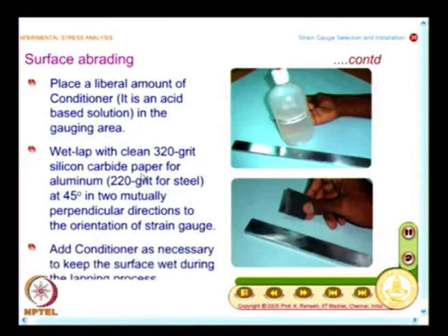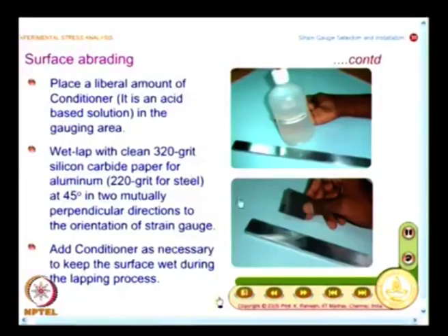And here you are not testing your muscle power to rub the surface with full force, that is not what is anticipated. What is anticipated is to prepare a surface which has sufficient roughness, and what they say is 12 strokes at 45 degrees and another 12 strokes at minus 45 degrees would do for preparing the surface.